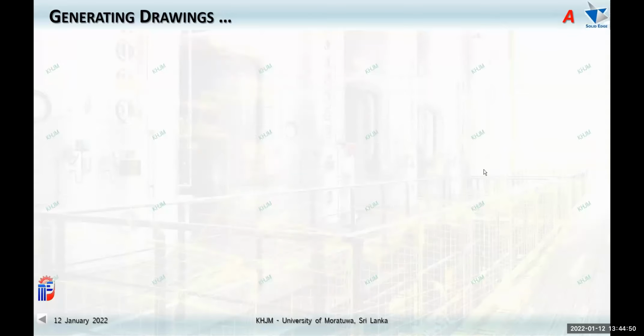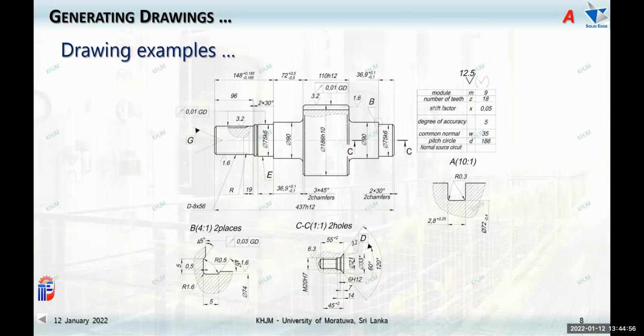And then you can see a different shaft. This is a shaft with an integral gear wheel. Look at how the diameter of the gear wheel is given, the outer diameter. 186 H10. H10 is the value you have to take from the tolerance charts. How much is H10? And there are different types. One is called the hole basis, the other one called the shaft basis.